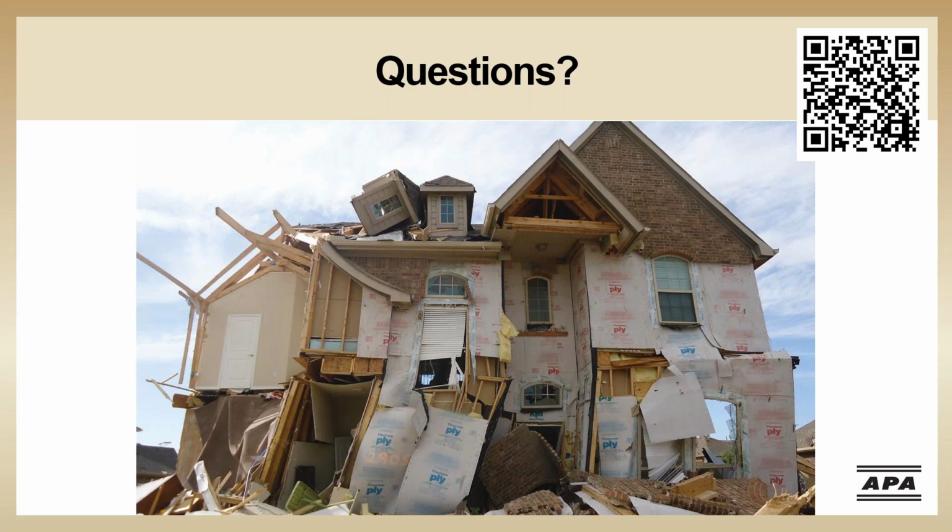In typical residential construction, brick cladding is attached to the house with light gauge metal straps that span from the exterior sheathing into the brick veneer. They span across an air gap, actually. So there's a gap between the brick and the exterior sheathing. And those straps are light gauge. They do not have the strength that you would need to transfer that wind load into the brick. Because of that, there's no way for that brick cladding to be a part of the lateral load path, so it cannot contribute to the lateral strength of the house.